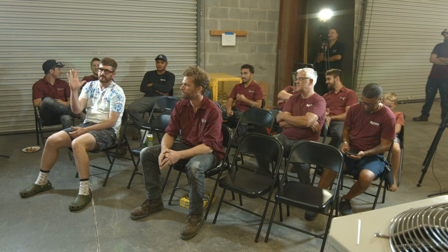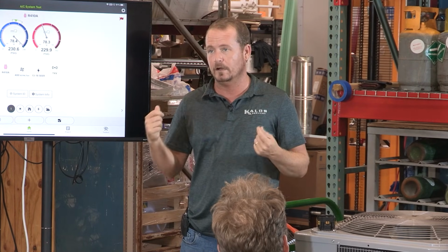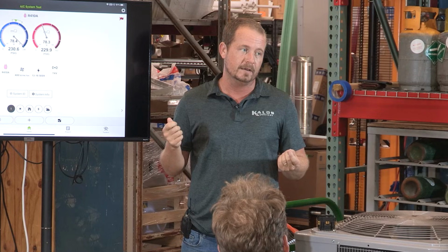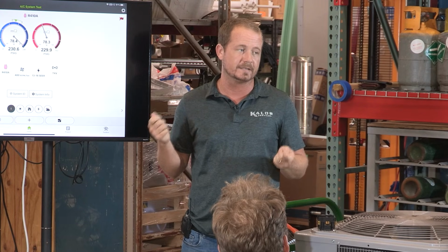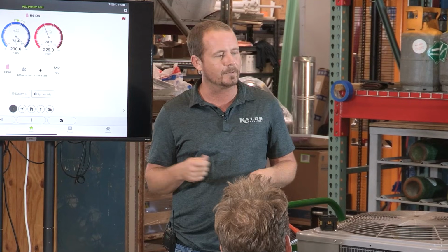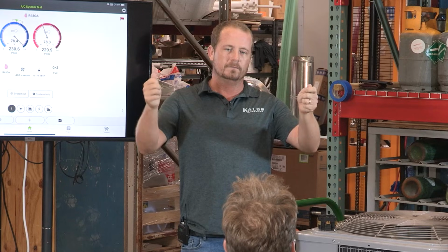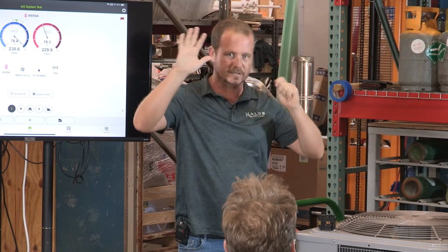We also have insulation in the unit sucking into the blower. Yes, I was waiting for that one. Insulation in the unit that sucks up against the blower. That's another really big one. Every time you take the panel off of a system, and by the way, it's actually pretty dangerous to take the panel off of a running air handler. When I say dangerous, it's probably not going to kill you, but I've seen people pull panels off, the insulation sucks off, and then it starts shorting out or gets into the blower or whatever.